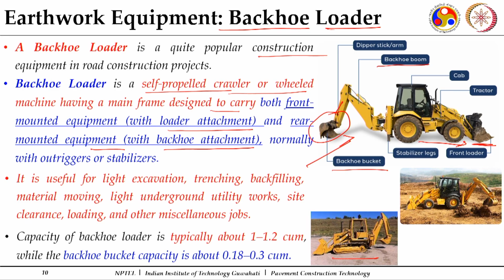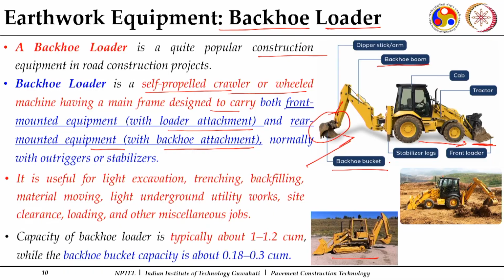So, it can pick up, it can dig, it can cut down, it can pick up the material and shift the material from one place to the other. In addition to this, when working on challenging sites, we have these stabilizer legs also to stabilize it. So, it can work on sloping grounds also with the help of these stabilizer legs. It is useful for light excavation, small scale excavations. If big scale excavations are there, we can have the hydraulic excavators.